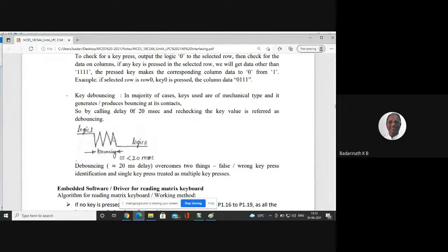To avoid this area, what is the method? It has been identified by many programmers and interfacing engineers that giving around a 20 millisecond gap will make sure your system works perfectly. As soon as you identify a key, give some time before reading the next key. This allows the bouncing to be avoided. Actually, in the program we should allow 20 milliseconds and then read again, but to simplify the program, I'm just giving one 20 millisecond delay.